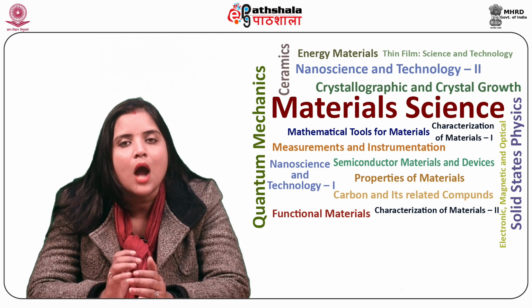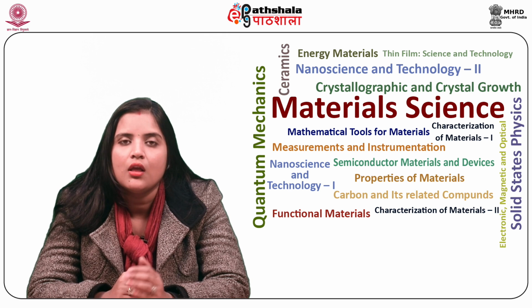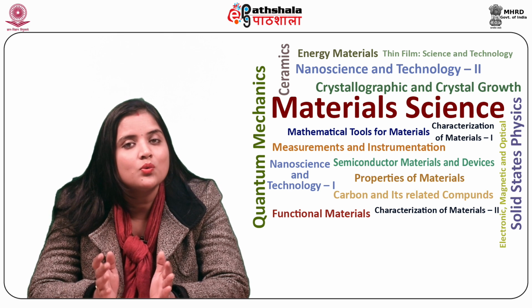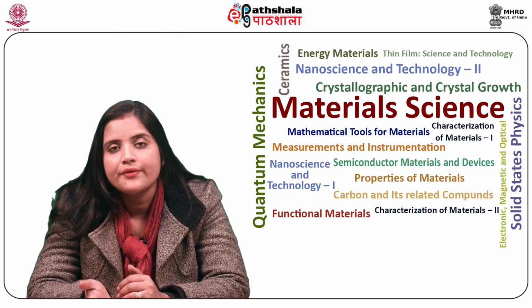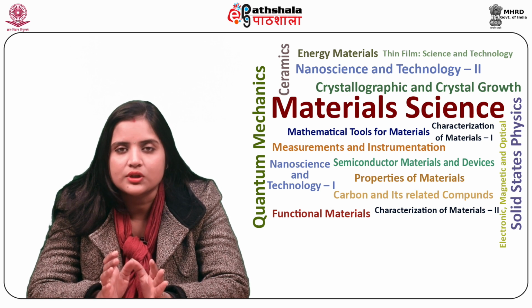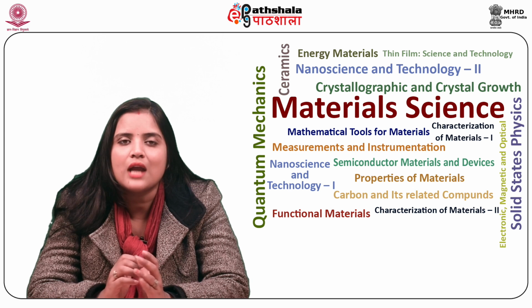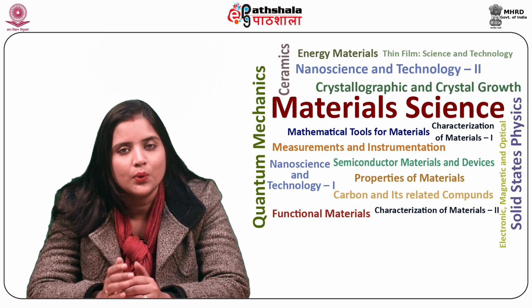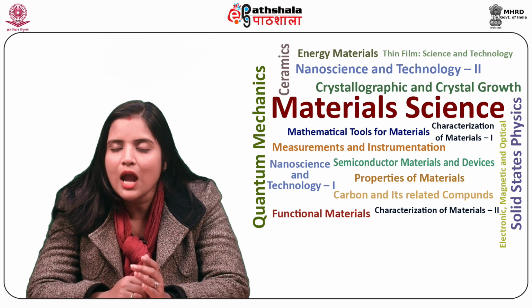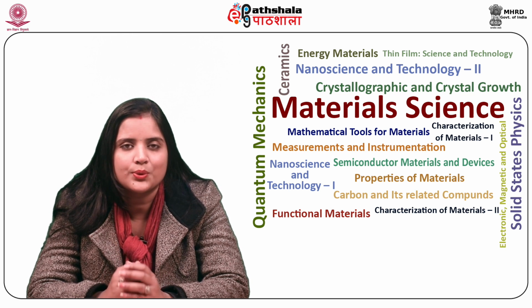Precursor materials are vaporized at high temperature and low pressure conditions. These vapors are then transferred by inert gases to lower temperature zone where they progressively supersaturate. When they reach the substrate surface, nucleation and subsequent growth of desired nanostructures takes place. The growth can be terminated by turning off the furnace. The reaction setup is cooled to the surroundings by flowing inert gas through it.